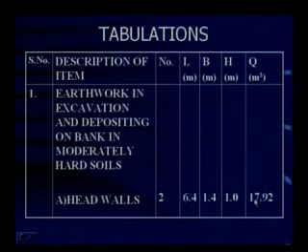So how do you get the quantity, or in terms of volume? That is in meter cube, because for convenience all tabulations are being made in meters. As you know, L into B into H will give you the quantity. The quantity here is 17.92 cubic meters.